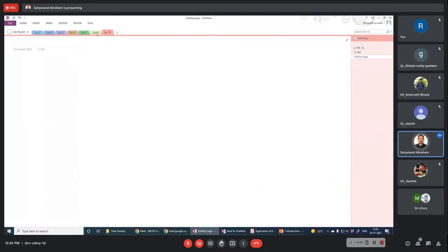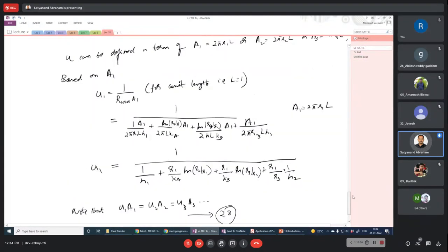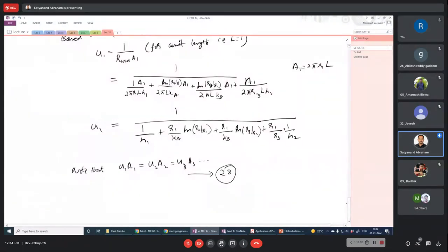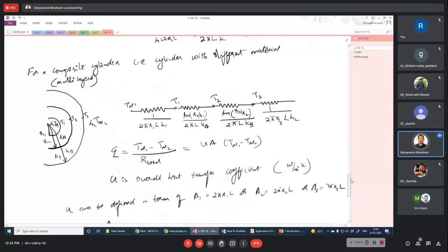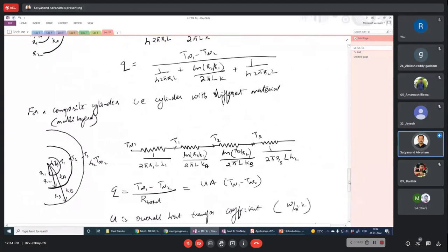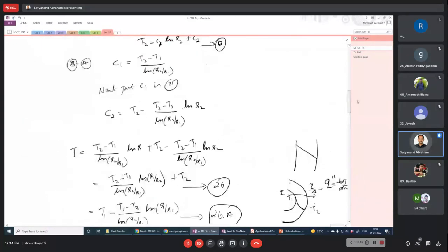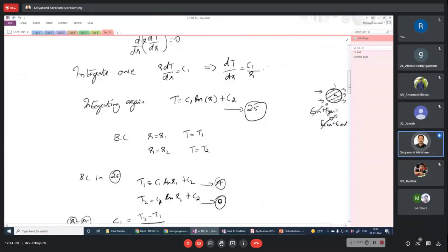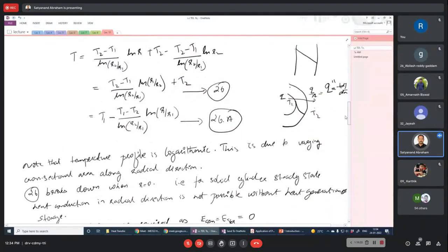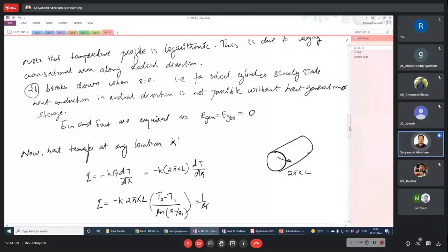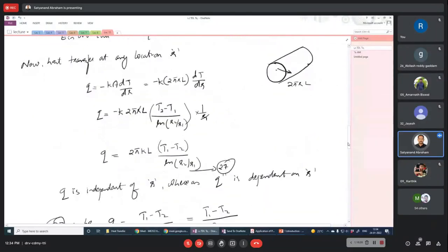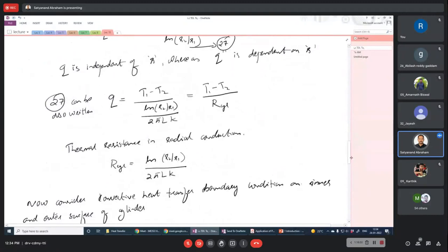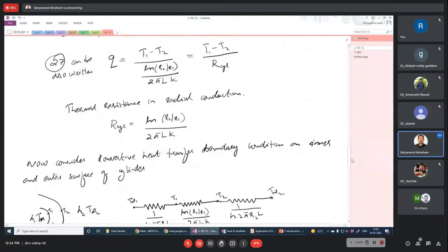So till now, how have we been doing these things? To find the temperature profile and then the heat flux, we were writing the basic equation, and then using the boundary conditions we solved it and got the temperature profiles. Then differentiating the temperature profile, we get dT by dx, and based on that we calculate the heat flux and further things. So it is a very good method, and that is how we can do this.